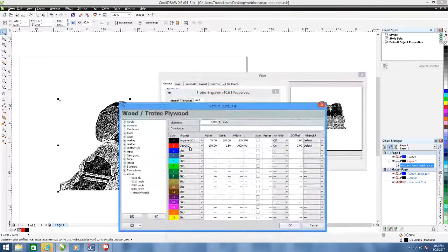I'm going to come in here on acrylic. I'm going to use a lot less power on acrylic because I don't want to have any depth. I want a nice white image. I'm going to use 35 power for my acrylic, so now I'm using half the power that I'm using for wood. And again, this is because I've tested for the acrylic and I know what power and speed to work with.